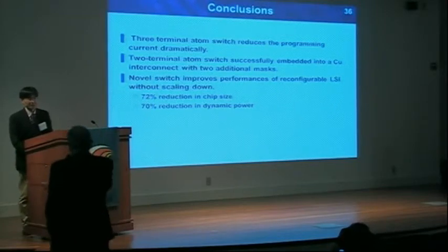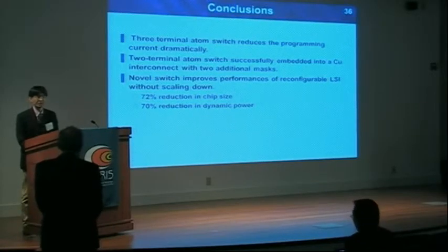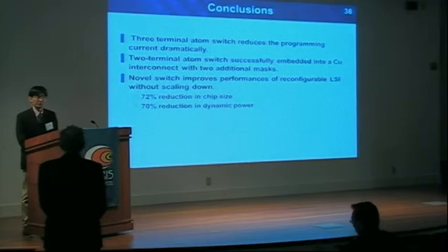So as I explained, there is a trade-off between the set voltage and off reliability. So to ensure the off reliability, we need a higher voltage. But you're right. We need a high voltage transistor. So the high voltage transistor occupies 70% of our logic cell. So we need to reduce the area of the transistor, I mean selector transistor. We want to reduce to 1.8 volt.